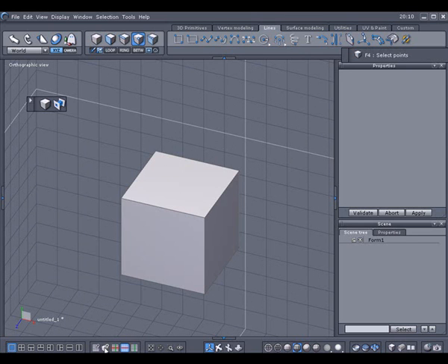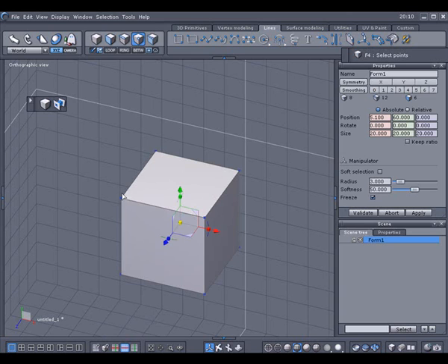So let's say we need to switch this back over to snap to every half edge. If I was to insert a point, it's going to snap to every half edge between 2 points. What that means is from this point to this point over here, it's going to try to snap in between it.